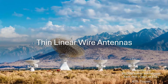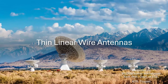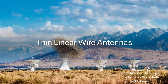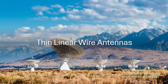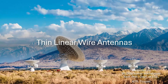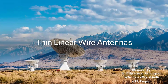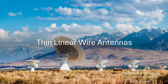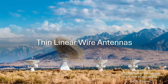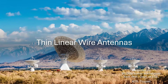Generally, they are very small in size. Even the diameter is less than 1/100th of the operating wavelength, allowing us to assume that the current flows only along the length of the wire. Wire antennas are among the simplest and most widely used antennas because they are easy to design, low in cost, lightweight, and efficient for transmitting and receiving electromagnetic waves.